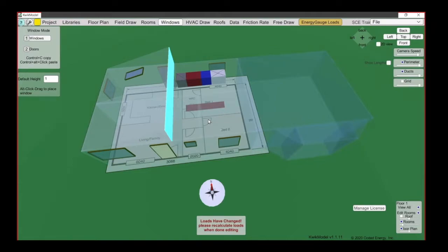And if you came to the introductory class that we did a month or so ago, I had the example of how a house is like a tank of water. The water was escaping in 3 ways, and we had to size a pump to replace the water, and we had to calculate how much water was leaking out, how much was seeping out, how much was evaporating, so that we could size our pump. Well, that's an analogy of doing a load calc to size a furnace. And instead of water, it's BTUs escaping from the house.